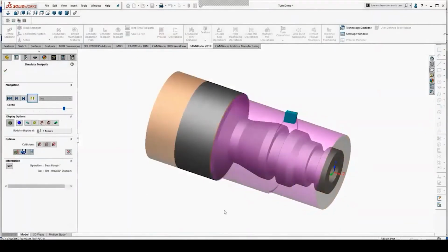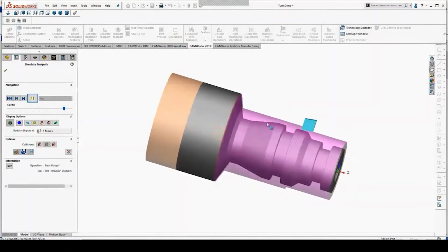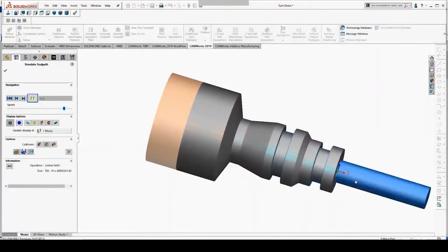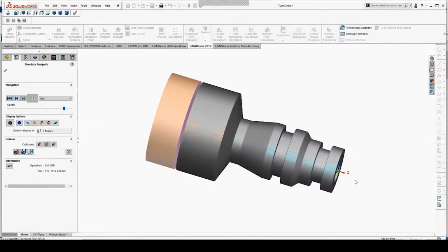And when I was talking about the CNMG and the clearance, this is what I'm talking about here. It's going to leave stock because it's aware of the geometry of the tool. And you saw the DNMG that followed cleaned it up properly. So it does select the right tool pathing or the tool strategies, the right tools to accomplish those strategies, and it will tool path correctly automatically.